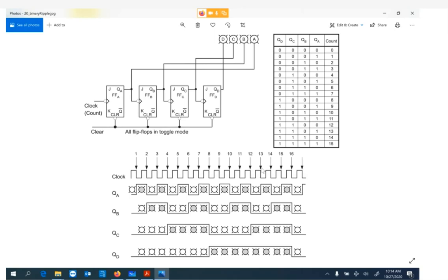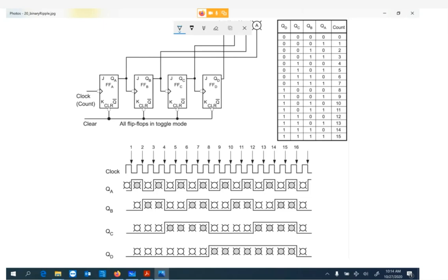Yeah, so you'll notice here, if I can write on it, that kind of zoomed it in. Cool. This is our 0 count, 1, counting in binary, 2, oh, there it is on the side. It's all written on the side over here. So all 1s. Let's shrink this back a bit. There we go. So this is our least significant digit, A, 1, 2, 4, 8. So when they're all on, we can see it counts to 15.